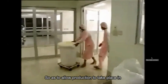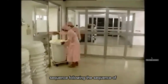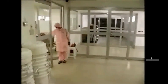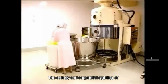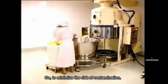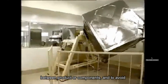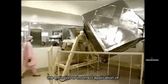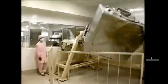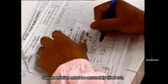Premises should be laid out so as to allow production to take place in areas connected in an orderly and logical sequence, following the sequence of production steps and the requisite level of cleanliness. The orderly and sequential siting of equipment and materials should be done so as to minimize the risk of contamination and to avoid the risk of confusion between product or components and to avoid the omission or incorrect application of any of the manufacturing steps or control or handling procedures. Throughout the whole process, documentation must be accurately filled out.